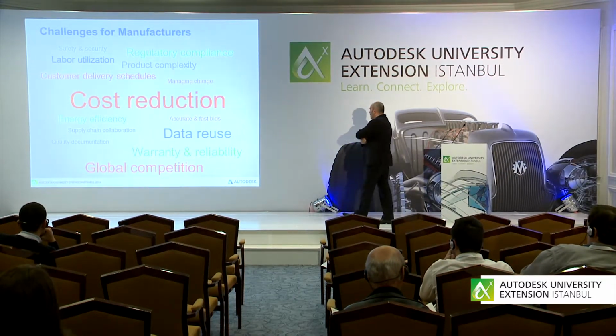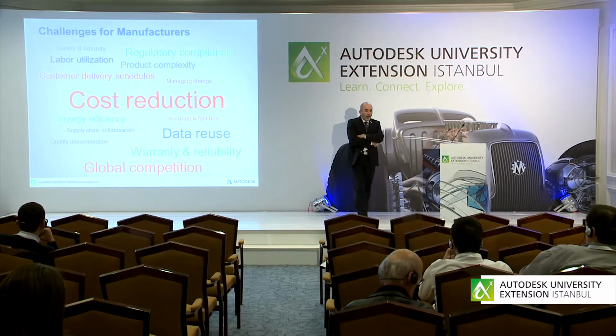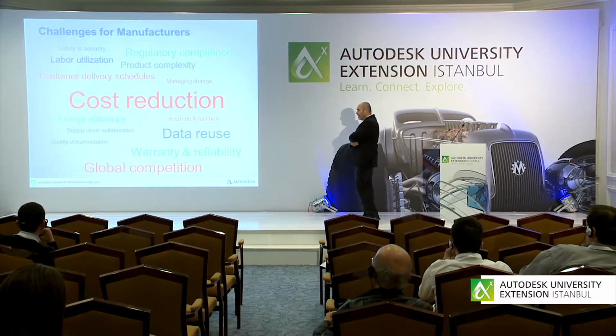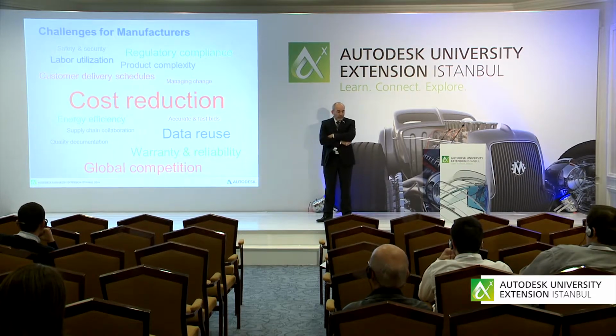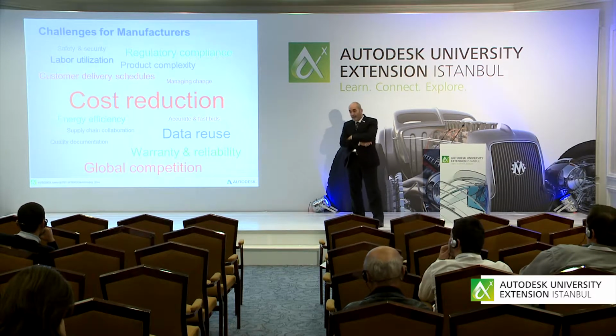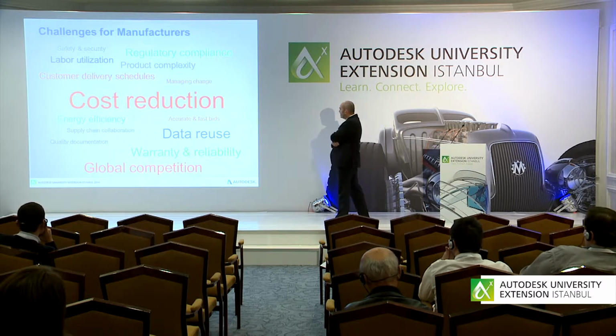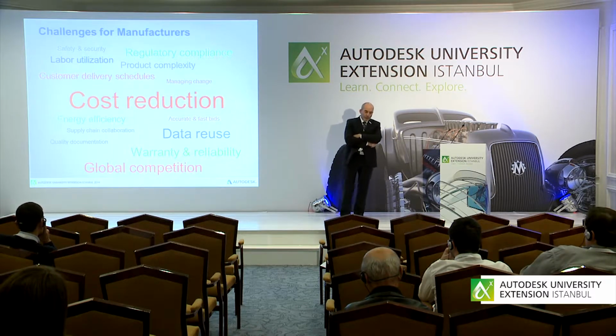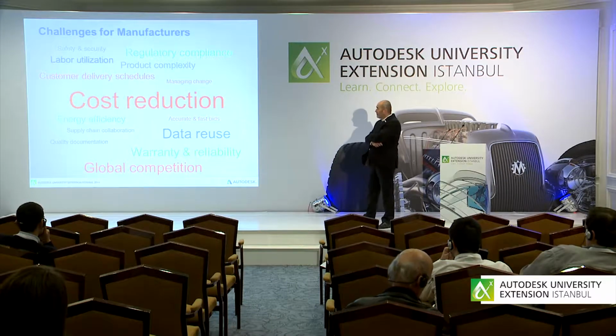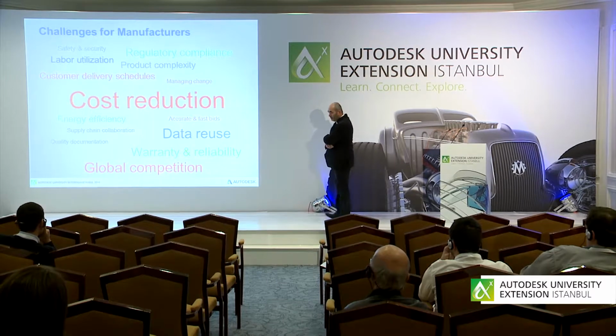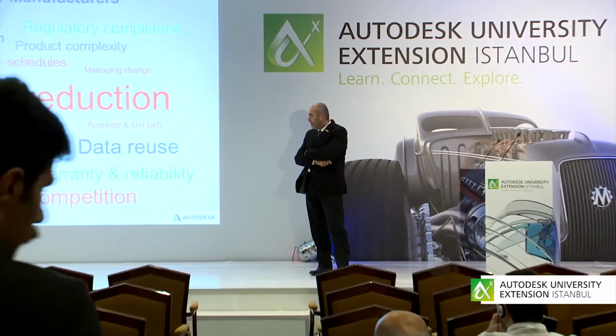I give an example. Quotation process. You have to provide accurate and fast bids. A customer provides you, hopefully, a 3D model that you can import into Inventor HSM. We have a lot of interfaces like STEP and IGES to do that. On top of this imported 3D model, you can generate a CAM project. After you generated that CAM project, you receive the machining time, the time how long it takes to machine that part. You should add additional costs like stock material, maybe tooling costs, and so on. That leads you to a final price per part for a customer and to an accurate and fast quotation for your customer.